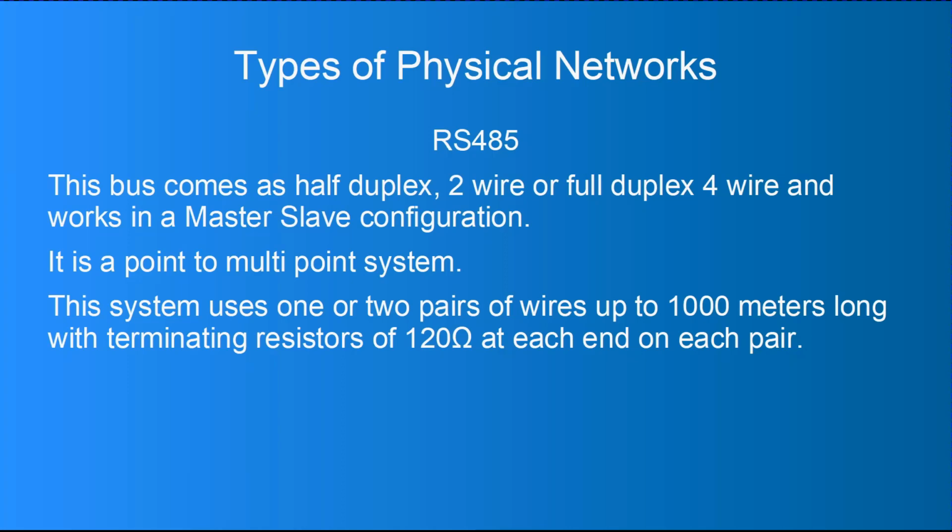It usually runs at around the 5 volt mark as well. So when you're transmitting logic 1, wire A will be at 5 volt and wire B will be at 0 volt. When you're transmitting a logic 0, wire A will be at 0 volt and wire B will be at 5 volt. All we need to do then is actually look at the difference in voltage between the 2 wires,